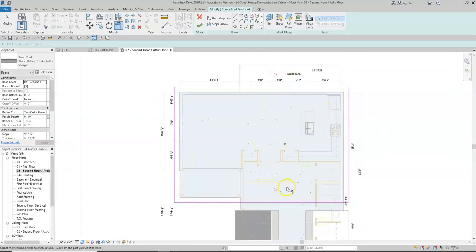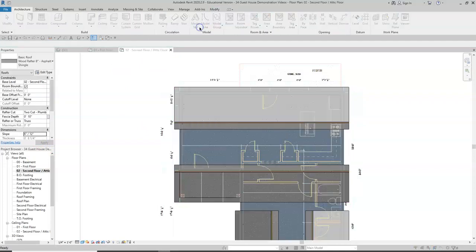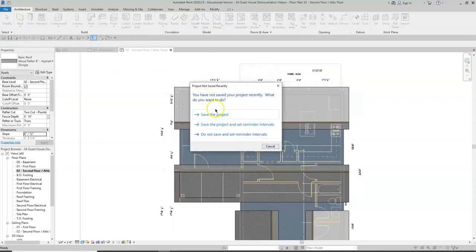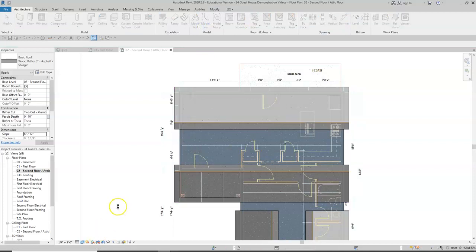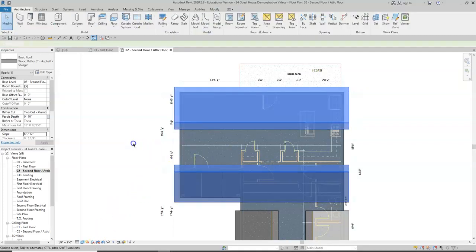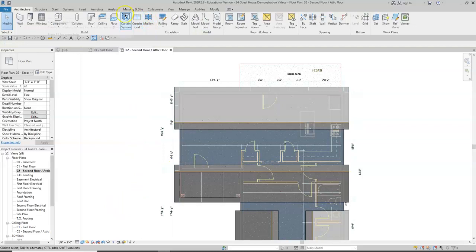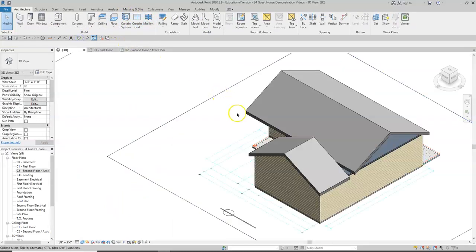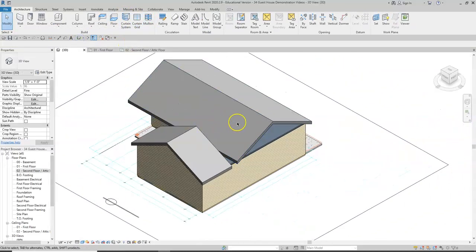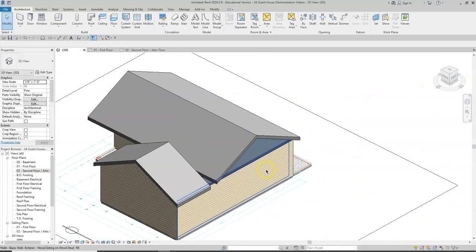All right, we have our Define Slope set. Our pitch is going to be 6/12. We can change it here once. Click Apply and green check. And we have a roof. We go to 3D mode and our roof is displayed on the screen.